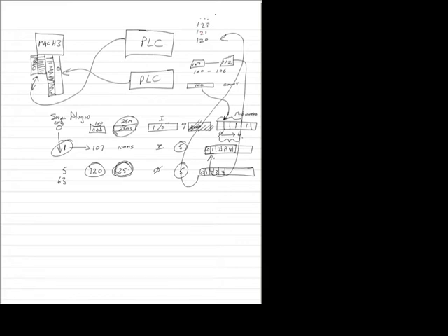You get the idea. So this configuration of serial plug-in is somewhat more powerful than the old serial ModBus. And if you're not using special processing with a Mod.io, it may be the way to go, or if you want to design your own Mod.io plugin. The weakness here is that there's no way yet to send a string to the Mod.io, so you can't use the LCD display on it the way that you can with the old serial ModBus.